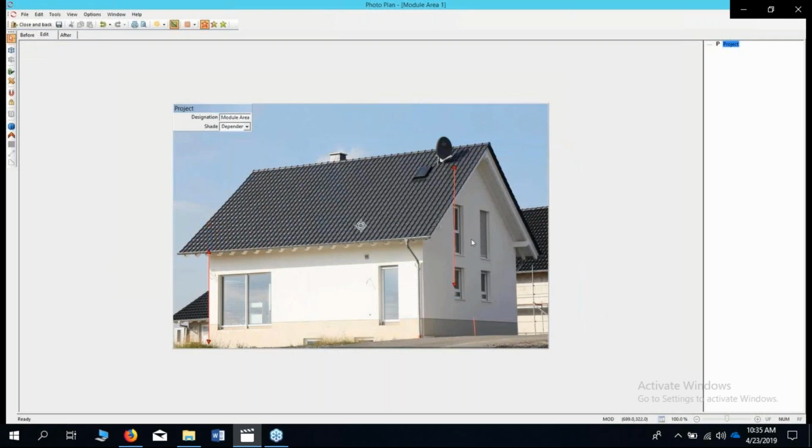Change the length of the arrow, and then you have to bring the other arrow to another edge of the building. And now the vertical axes are defined, and what we have to do in the next step is define a geometry. And therefore we have to click the small cube here on the upper left hand side in this icon bar to create a new layer. And therefore you have to click into the edges of the roof.